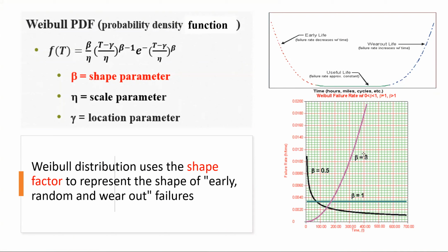So using beta only, keeping the scale parameter the same, you could see that beta is adequate to describe the falling from the early life, which is beta 0.1 here, all right? And then this beta equal to 1 is your useful lifetime, and the wear out is gradually decreasing. Everything is going to the end; everything must die eventually. So that was the kind of intrinsic failure of the device, of the package, right?